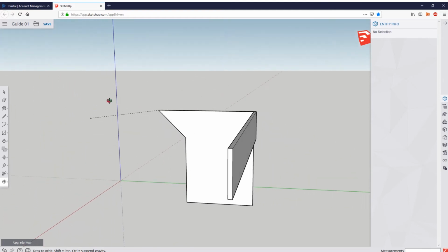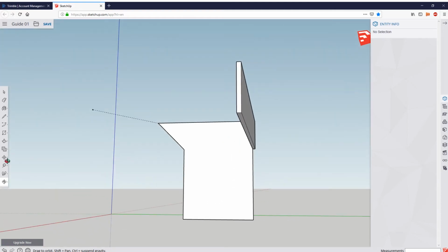Ignore what I just said. Let's say that you want it to sit from under. So you want this part to sit on top of the bottom panel. Just an example. Then you have to measure from this side here until here. Then it's 51.8. That way, you already are taking into account how wide the wood is, its width, and you have to take those measurements into account.